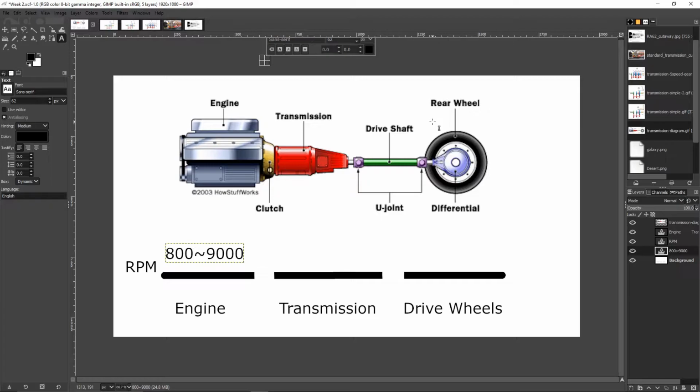If we put your manual transmission on a hill in whatever gear, let's just say we're cruising along in fourth gear and we hit a really steep hill, and gravity starts pulling us, momentum speeds the vehicle up. Without touching the accelerator pedal, the momentum of the vehicle is going to cause the engine to rev up, because the drive wheels are attached mechanically to the engine and they are accelerating, which will cause the engine to rev up. On the flip side, you've heard of engine braking, and this is the idea that I'm going to downshift in such a way that it will mechanically link the engine to the rear wheels, and without me giving it throttle and asking for more power, it's going to rev the engine up, but the engine has to fight the compression stroke, and that is why you get engine braking.